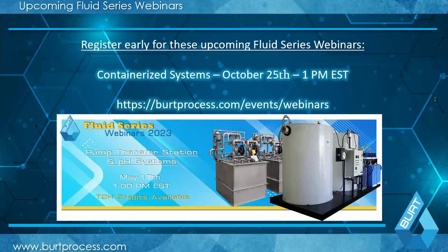If you're using drums, you're going to have a suction line that you have to remove from the empty drum. It's going to have a check valve. It's going to have some form of chemical on the outside of it as well as in it. Then you put it into a new drum. It really comes down to preference. I think having chemical tanks is cleaner than wheeling up fresh drums and having a spill pallet below it. But again, that's based on my own preferences in those cases.